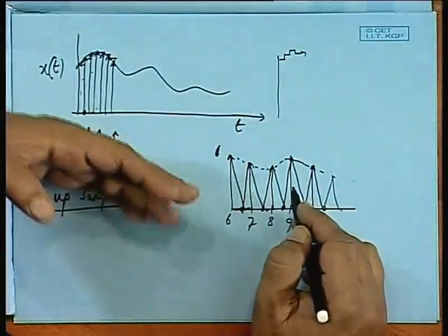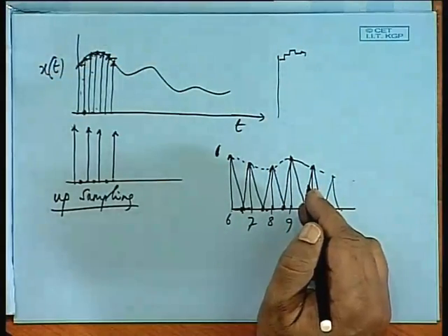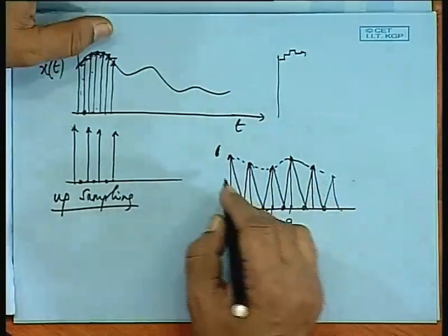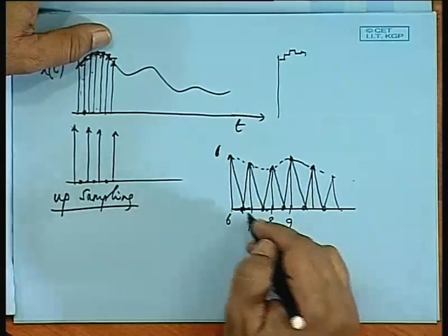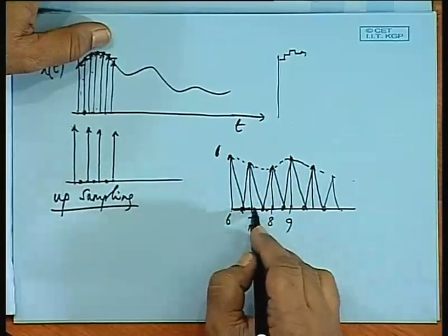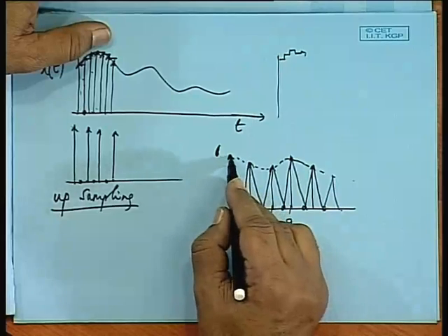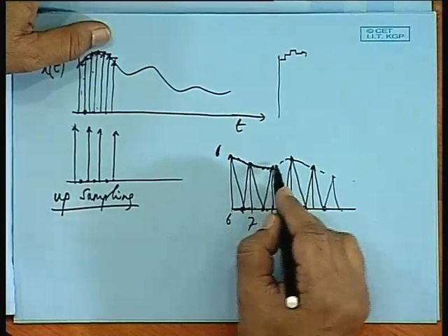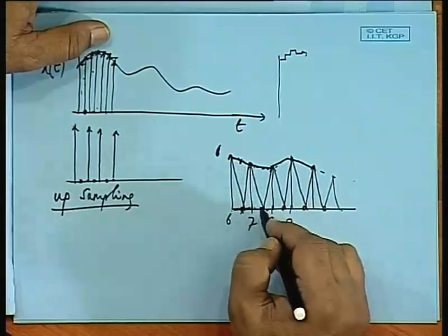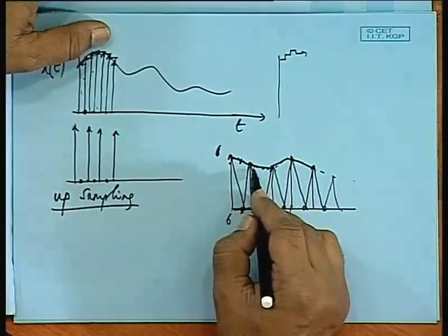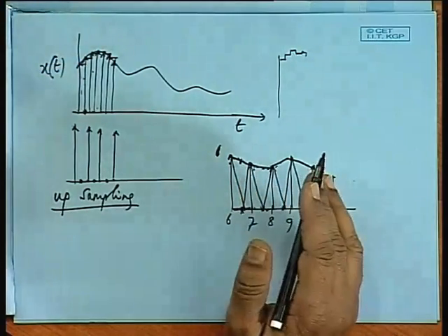If this sequence is passed through a low pass filter, then you can get back more or less the original sequence. One may insert some values by linearly interpolating, that is, take the values in between 6 o'clock and 7 o'clock, whatever values you want.